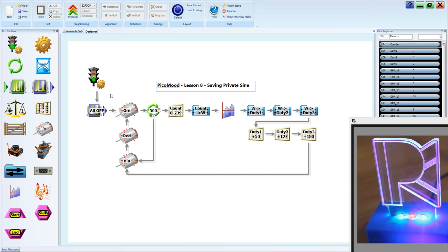Now, to do that, let's try and just understand what we've done with this program so far. There's 4 stages. The first stage is start and turning the pins all off. That's a bit of an easy one to think about. The next stage is this motor tool stage that's generating our pulse width modulation. And so at the moment we're running that through 500 times, and that's really quite a fast value to go through 500 times, and then it goes and looks up the rest of this just once before it goes and does this section 500 times again. Well, that's stage 2, we could say.